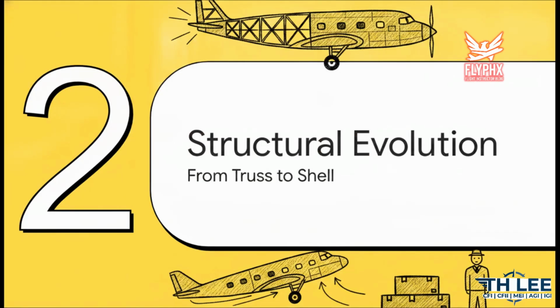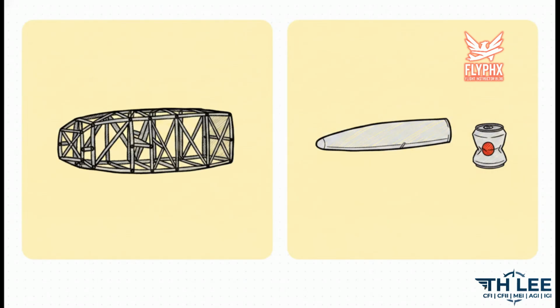Section 2, evolution of aircraft structures. So, this brings us to a really fascinating evolution in structural engineering. Early aircraft used what's called truss construction. This was basically lengths of tubing, called longerons, welded into a well-braced square or rectangular framework. The main drawback? A total lack of any streamlined shape. Designers literally had to add extra formers and stringers just to shape the cloth fabric covering over it.